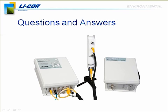And something that's really new and exciting about the 7200 that's different from any other analyzer on the market is that now we can integrate sonic anemometer data, and we have onboard data collection. So now, with the LI-7200, we provide a complete solution for fast eddy covariance measurements. You can input your sonic data and collect it right alongside the 10 or 20 hertz data that you're collecting from your CO2 and water vapor analyzers.